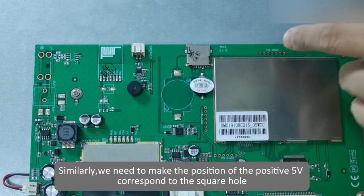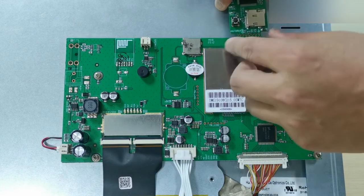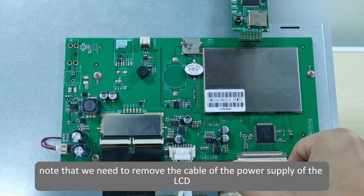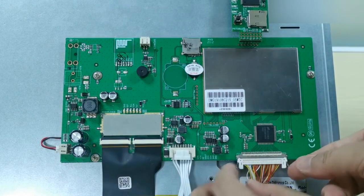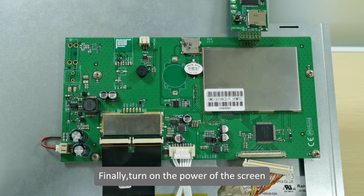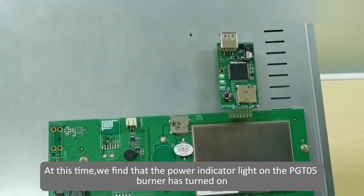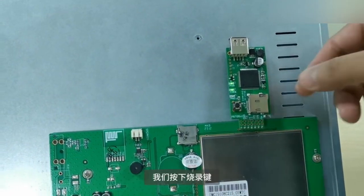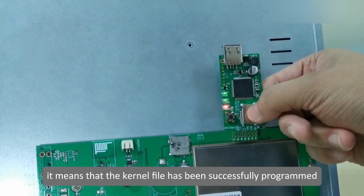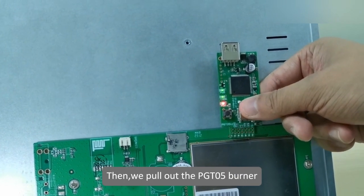Similarly, we need to make the position of the positive 5 volts correspond to the square hole. Then, before programming, note that we need to remove the cable of the power supply of the LCD. Finally, turn on the power of the screen. At this time, we find that the power indicator light on the PGT05 burner has turned on. Press the programming key. When the red light turns on, it means that the kernel file has been successfully programmed. Then, we pull out the PGT05 burner.